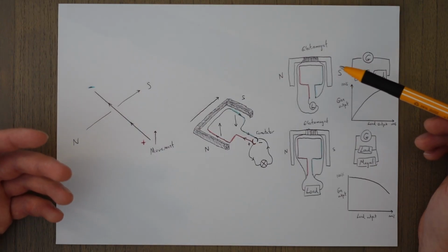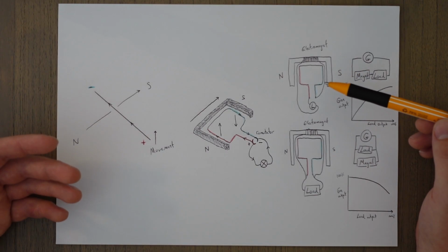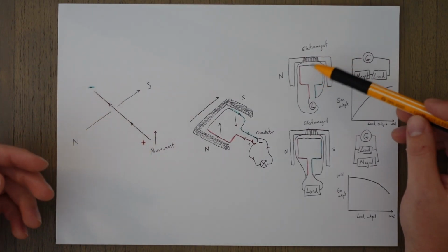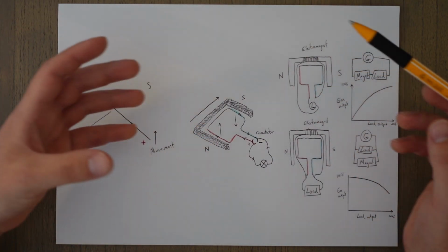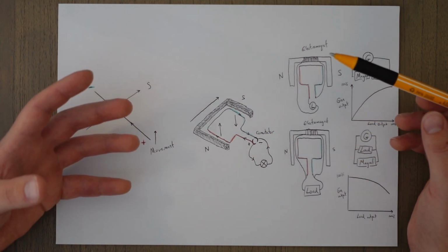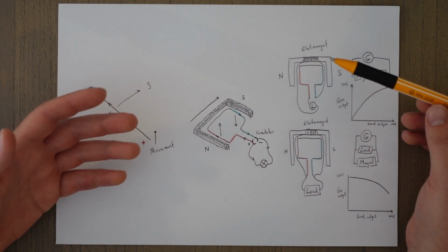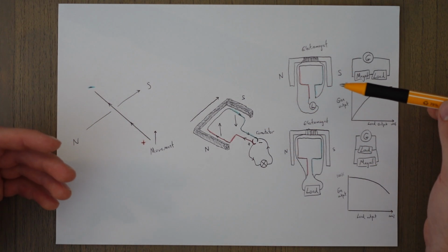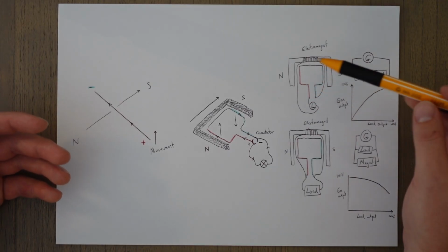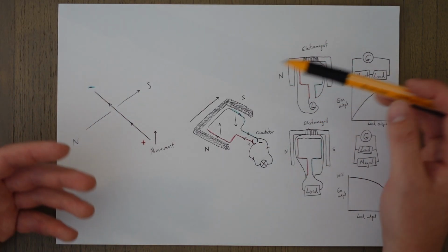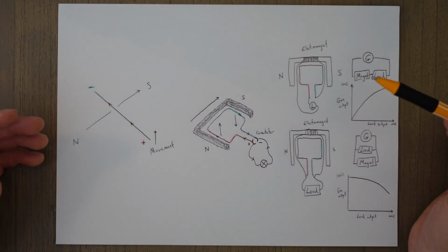However, this is an electromagnet, so we do need another source of power to create the magnetic field in the first place to begin the generation process, like a battery or something. But once the generator is up and running, we can just tap into some of the electricity generated and power up the magnetic field from the output of the generator itself, hopefully that makes sense.